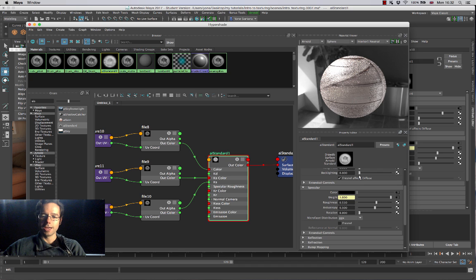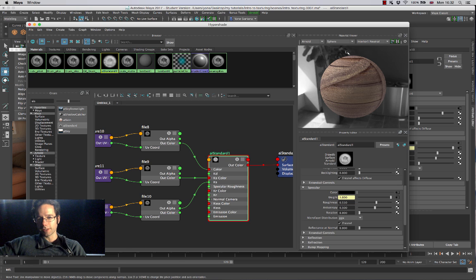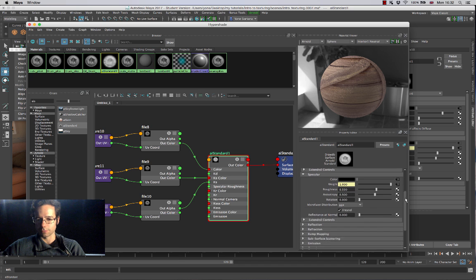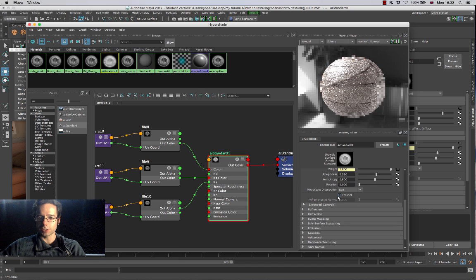It's still very glossy. But if I turn this option here, which is called Fresnel, on, and I click on it, you're going to see that now it's going to look a lot dimmer. And the reason for that is that the Fresnel is only going to make it reflective if the light actually hits it at the right angle in respect to the camera, and that's going to help us a lot in terms of actually seeing that. So we'll see some of this glowiness on the actual material, but it's going to be really diminished thanks to this wonderful property here called Fresnel.